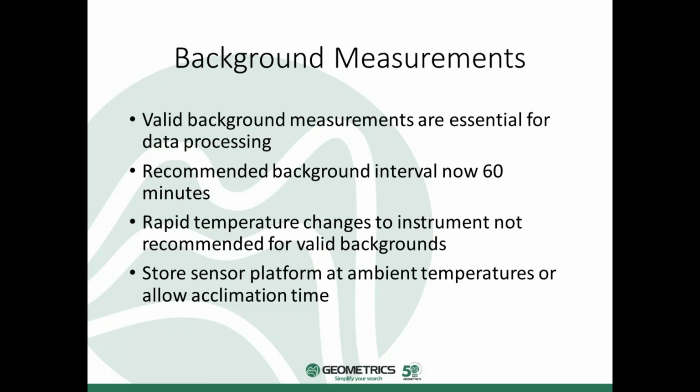And what the testers found was backgrounds taken immediately after the sensor was removed from the room temperature conditions into the very cold conditions changed over time quite rapidly. So Geometrics has also now made a recommendation to store the sensor at ambient temperatures or allow acclimation time.